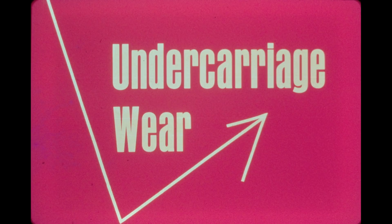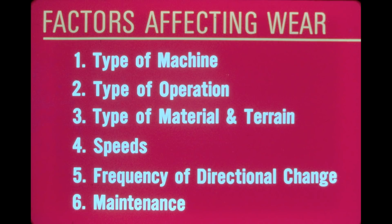Equipping the undercarriage with proper options will help extend undercarriage life. However, no matter what precautions are taken, the undercarriage does wear. Friction between the chain and front idler, top idlers, rollers, and sprocket will cause these components to wear, and the more abrasive the soil, the greater the wear. Here are some of the factors affecting undercarriage wear.